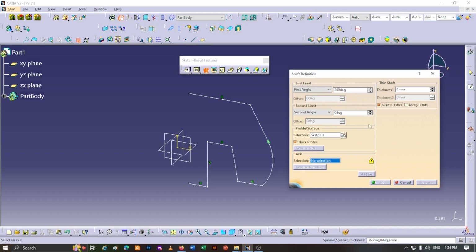On the left side and the fourth section, where axis is written, I had to select either an edge of the previous 3D body or one of the axes or a pre-drawn axis. Currently, the only available option for me is the V-axis. I click inside its selection box until it turns blue.